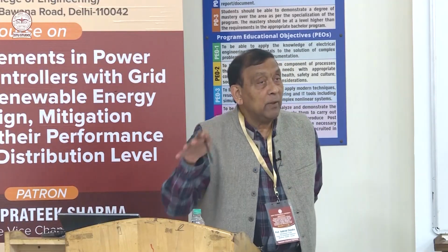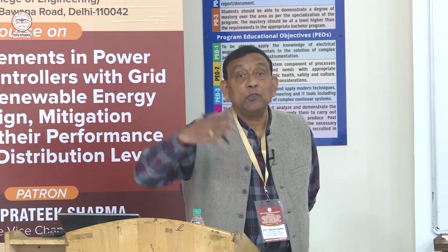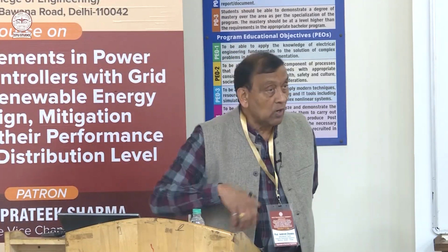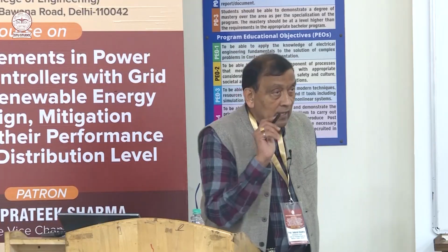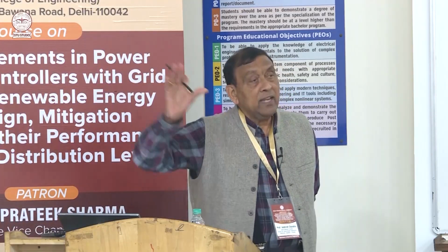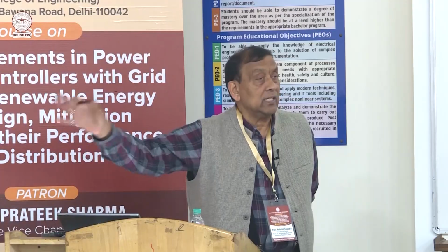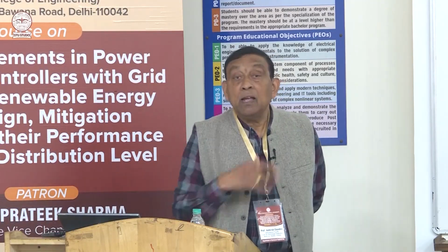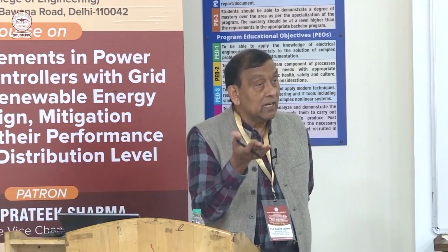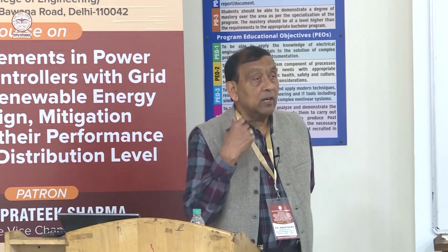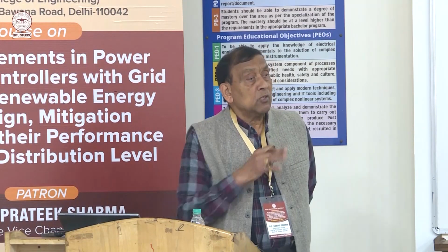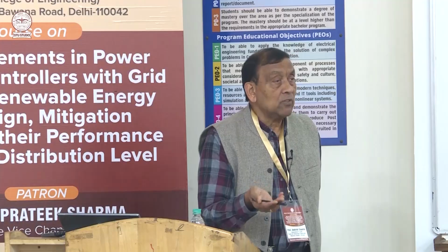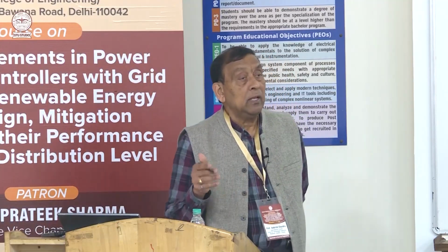If you have 1 big 3-phase transformer, does it mean you need another such big 3-phase transformer, which will cost a lot? But if you have 3 single-phase transformers, then you need only another small single-phase transformer to replace one if there is some repair. Moreover, it is easy to repair a single-phase transformer. It is very difficult to repair a 3-phase transformer. So these are some advantages and disadvantages of 3-phase transformers or single-phase transformers, right?